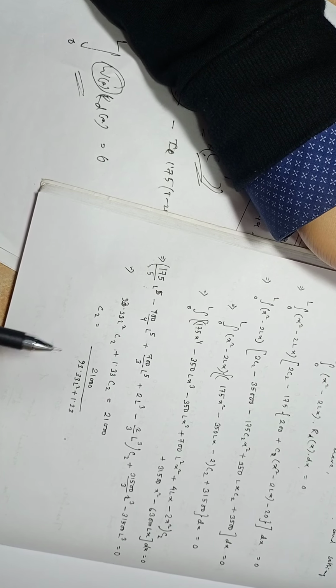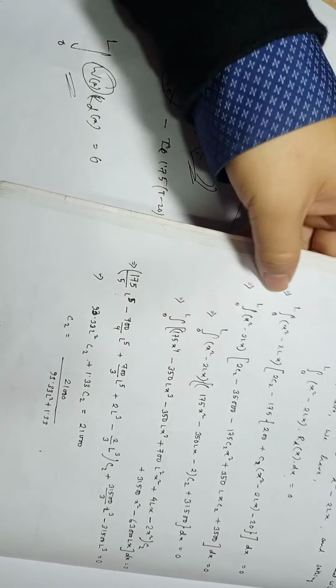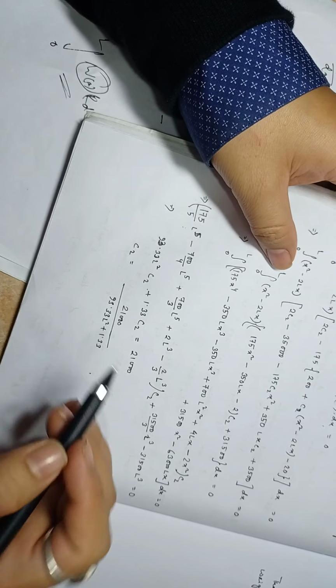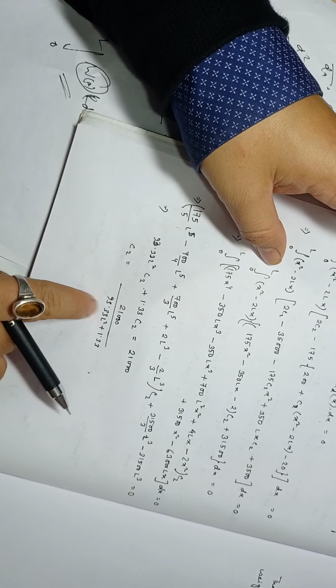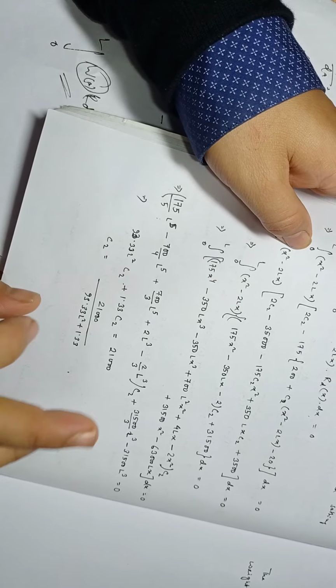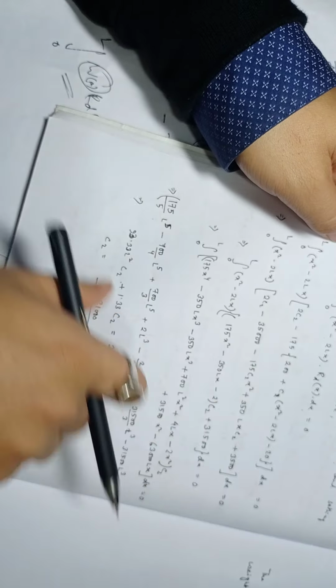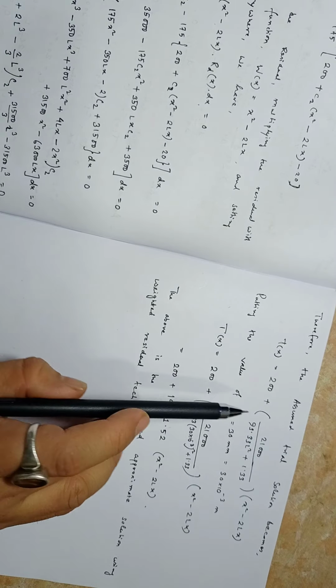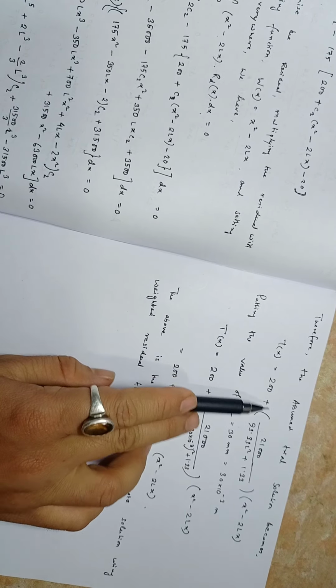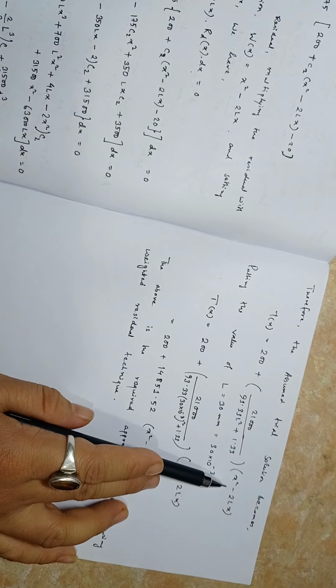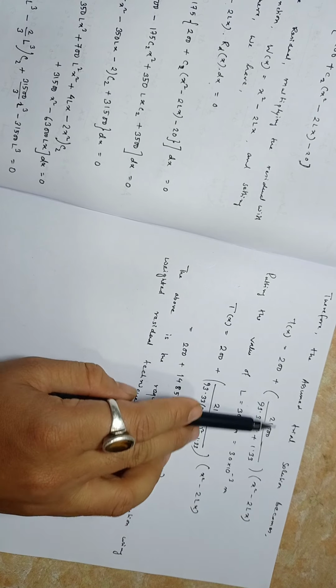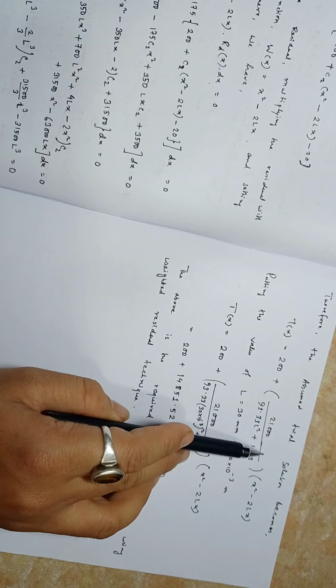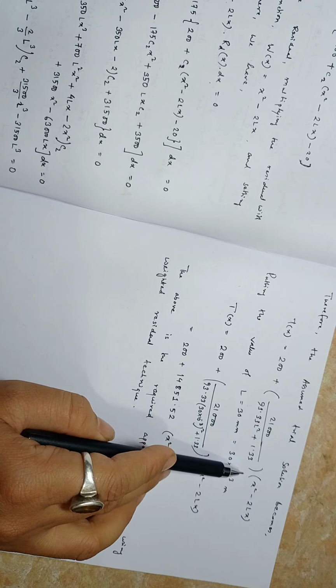So this is the constant we have obtained by minimizing the residual. So this value of C2 will minimize the residual for the entire domain. Okay. Now therefore the trial solution. Once we get the constant, we have to put it there. So 200 plus C2 into x square minus twice 2lx was there. So the C2 value is this: 21,000 divided by 93.33 L square plus 1.33.